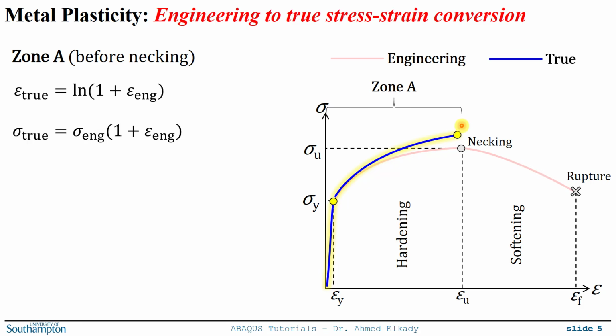And again, this makes sense because, as we mentioned, if I'm calculating the true strain, I divide the delta elongation by the total length of the specimen at a given time. But for the engineering one, you only divide by the original length, and the original length is always smaller than the current length. So that's why your true strain is a little bit smaller than the engineering one.